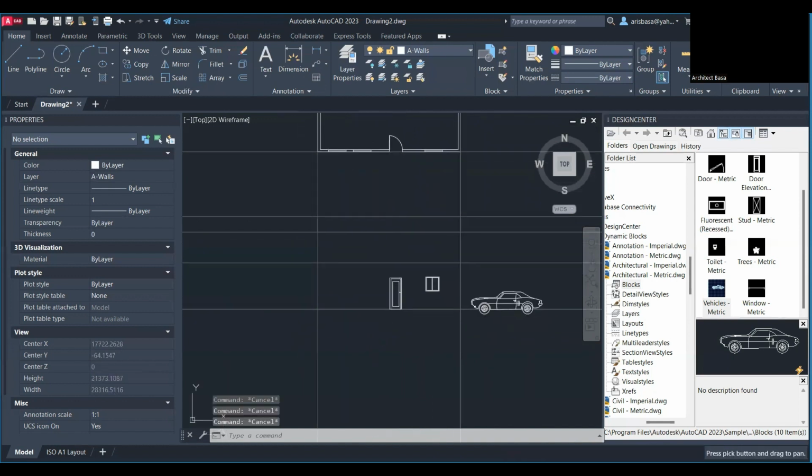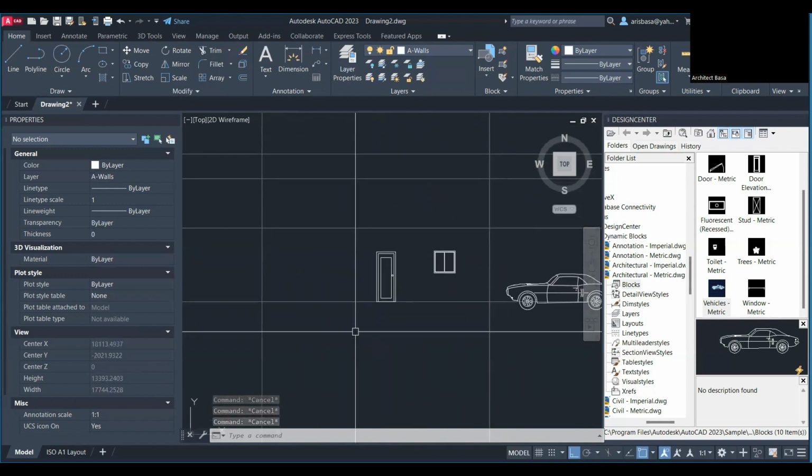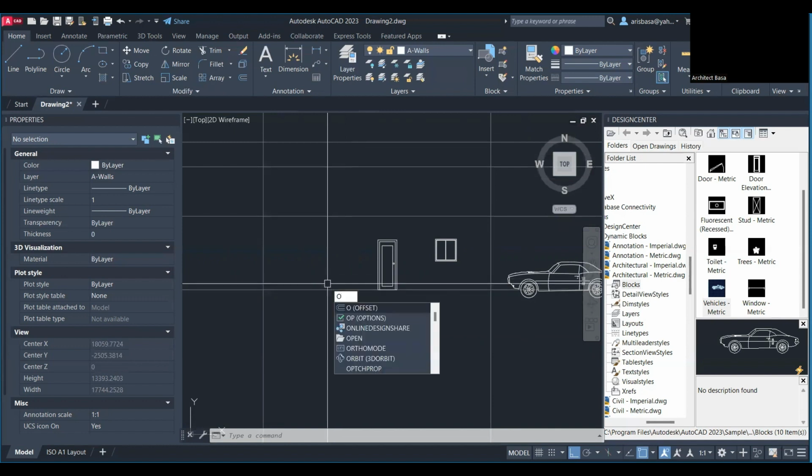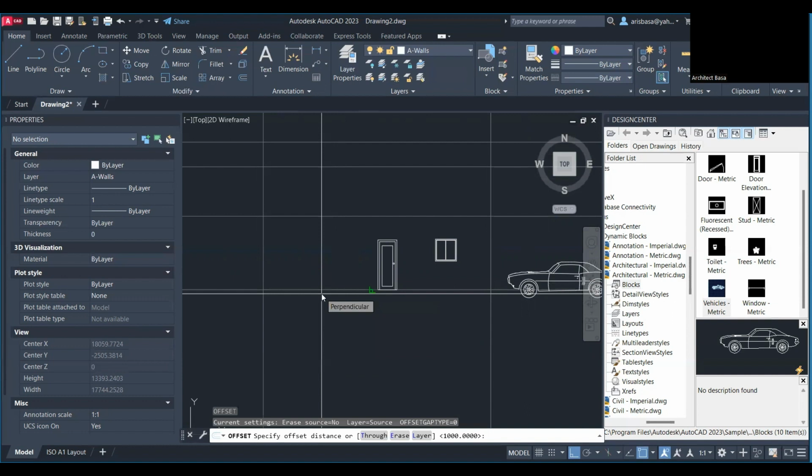So we're making the front view of your house. Let's have maybe 4 steps. Also, it's better that when you step 1, 2, 3, 4, there's some sort of balance. So 4 steps would mean how much, Madam Puja? One step is the riser, 150. So by 4, 600. So let's offset our X line 600 below. Okay, so let's offset. That's our shortcut, and that will be 600.